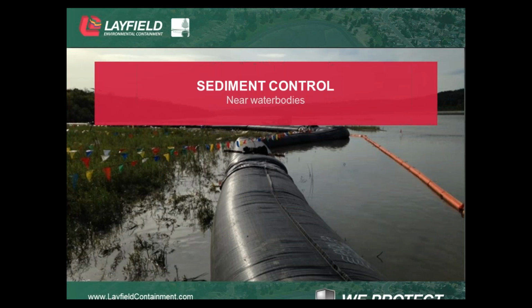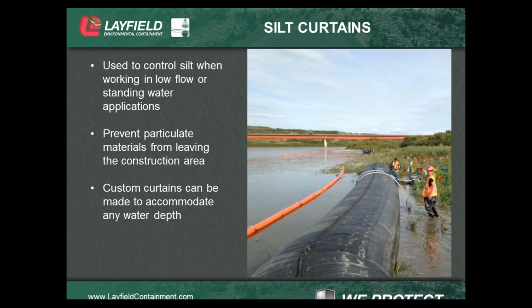So, sediment control near water bodies. Silt curtains, as Eric had talked a little bit about during the beginning of the presentation, are used to control silt when working in low flow or standing water applications. So you're working on a shoreline or something with very little flow or no flow. A silt curtain is going to prevent particulate materials from leaving the construction area, getting into your stream, contaminating it, and affecting fish or other types of wildlife, frogs, ducks, those kinds of things.